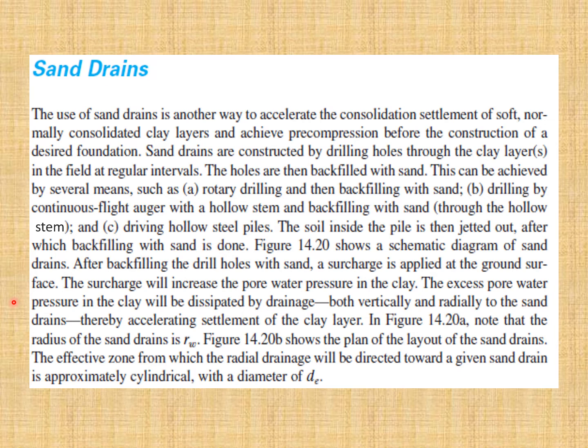So basically when the sand drains are introduced, you are having the drainage in the vertical direction as well as in the radial direction, thereby accelerating settlement of the clay layer. In the figure, note that the radius of sand drain is r sub w. Figure on next slide shows the plan of the layout of the sand drains.